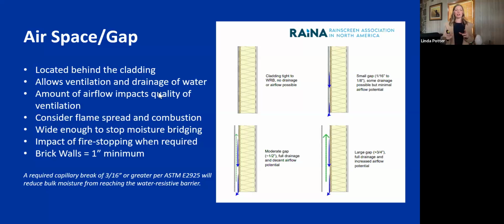The interesting thing is a brick wall has a 1-inch minimum. That's what the code of masonry tells you. But I think a lot of us understand that 1-inch minimum was determined because of the mortar that's getting smushed out behind that wall and dropping down that cavity and potentially getting stuck in there and causing some of this mortar bridging or stopping or thermal transfer, moisture transfer.